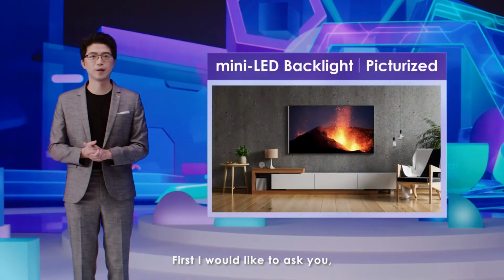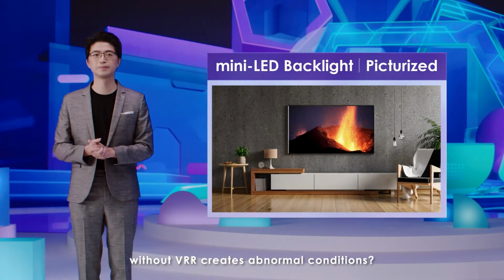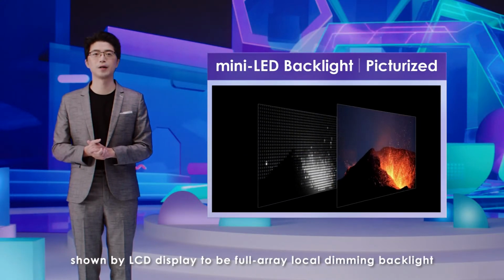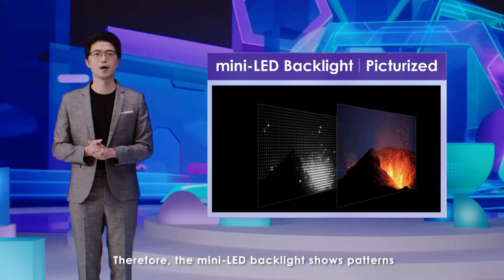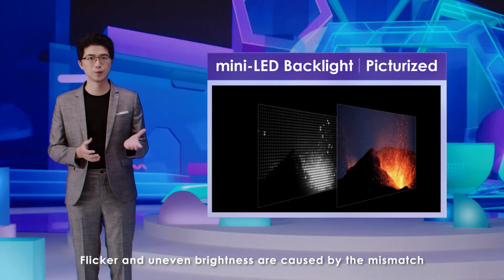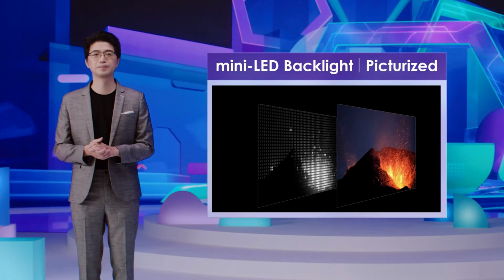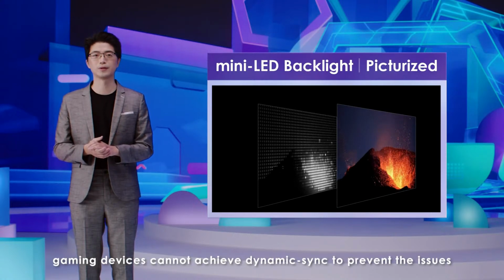First, I would like to ask you, do you know why the mini LED backlight without VRR creates abnormal conditions? It's because the mini LED backlight picturized the image shown by the LCD display to be a full array local dimming backlight. Therefore, the mini LED backlight shows patterns one frame by one frame. Flicker and uneven brightness are caused by the mismatch between the mini LED backlight refresh rate and the GPU frame rate. Without VRR, gaming devices cannot achieve dynamic sync to prevent the issues.